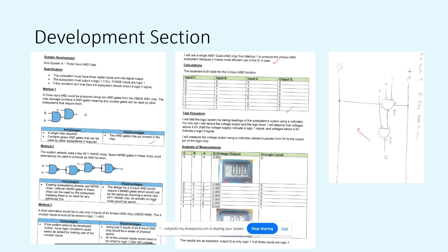However, if you've got lots of logic, you may end up saving space because you may end up with 7 NAND gates in use instead of an OR gate and an AND gate, which would be 2 ICs, which take up more space and more money. Actually, they're both 2 ICs, but you get the kind of idea.